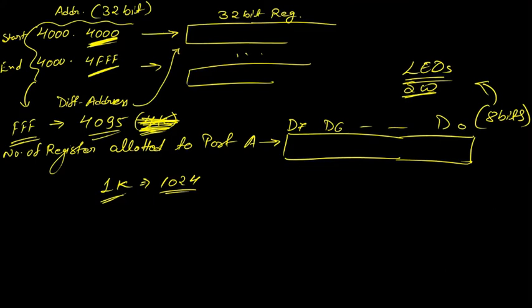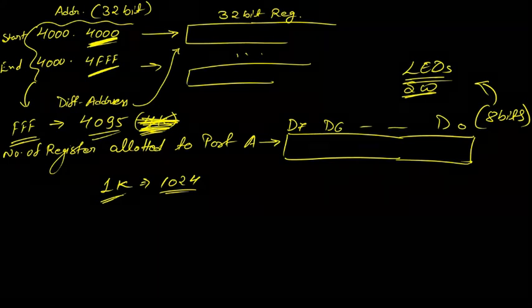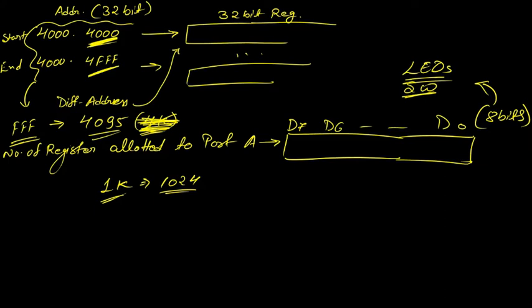So we will explore that, don't worry. This confusion comes, and definitely this should come to your mind: how come, just to control 8 bits, you need these many registers, and that too each register has 32 bits? 32 bits are there in each individual register. So why do I need 4095 into 32 bits, that many combinations, just to control 8 bits of port A?